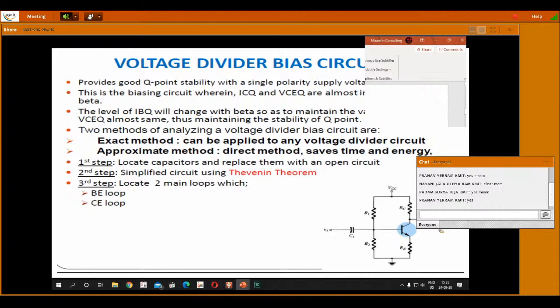So this is a single stage CE amplifier. Now, if I wanted to construct a multi-stage amplifier, then I have to couple my output through a coupling capacitor as an input to the next stage of the amplifier. So then we have the multi-stage amplifier.